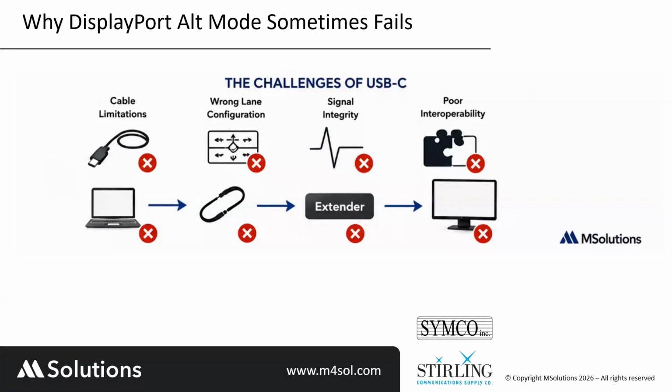Wrong cables, what does it mean? Not every USB-C cable supports the DisplayPort alternate mode. Some of them are defined just for USB 3 because they cannot transmit the full bandwidth requested by the DisplayPort. And some cables are designed only for charging and using USB 2.0 data. And I'm seeing a lot of confusion on that.